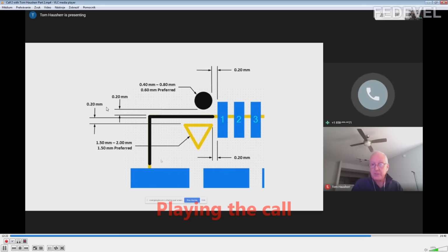You can't invert a resistor. You can invert a non-polarized capacitor, but you can't invert an SOIC, okay? And if you do, it won't work. So therefore, the SOICs are clearly stamped in the plastic where pin 1 is.